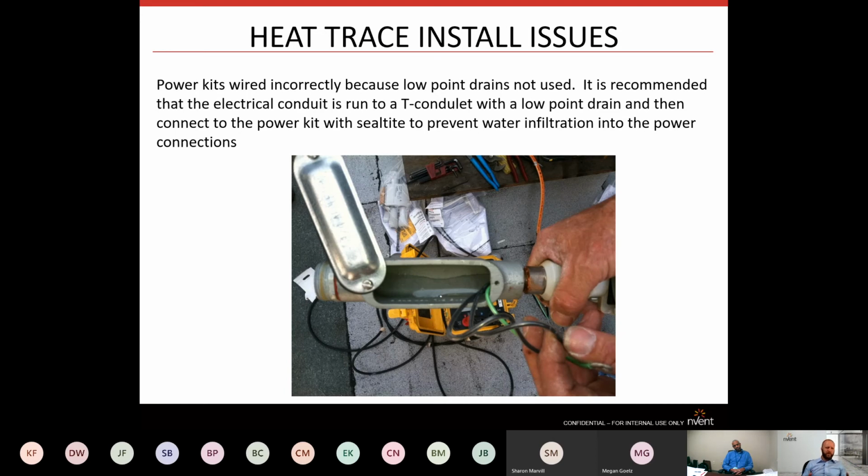So I always try to coerce people to think, hey, if there's a freeze up, let's look at everything. Let's not just say, oh, it's the heating cable, it's bad, someone didn't size something properly, and so forth. The first thing I typically go out and look at is the insulation system as well. That's typically the culprit.